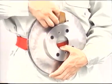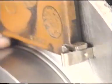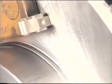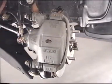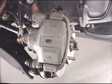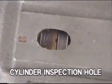When the pad wears out, the pad wear indicator makes contact with the rotor disc and makes a screeching noise during driving. Check the pad thickness through the cylinder inspection hole and replace pads if not within specification.